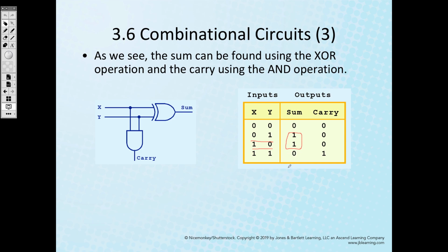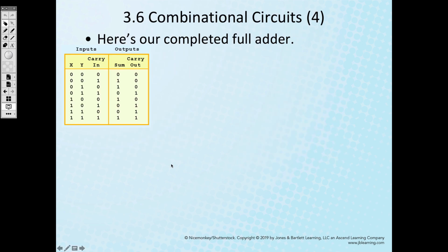That is what you have defined in the earlier stage, the XOR circuit. Another symbol we have is that, so we could use the XOR gate to implement the half adder directly. But here comes a full adder. So the full adder should be as follows. We need to take care of carry in as well.